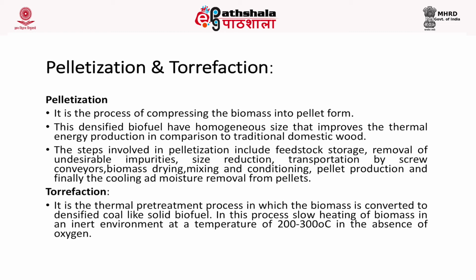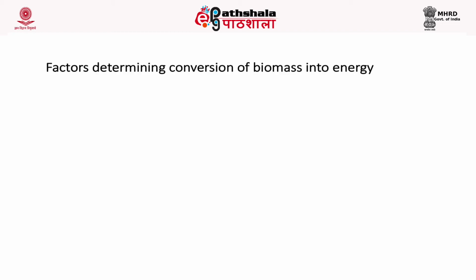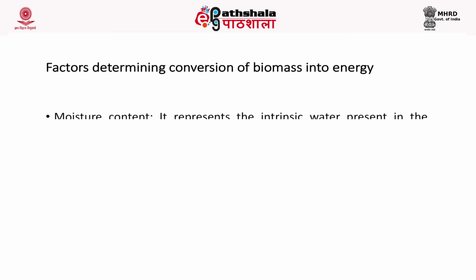Torrefaction is an advanced thermal pretreatment process in which biomass is converted to densified coal-like solid biofuel. In this process, slow heating of biomass in an inert environment at a temperature of 200 to 300 degrees Celsius in the absence of oxygen occurs. The factors determine the conversion of biomass into energy.